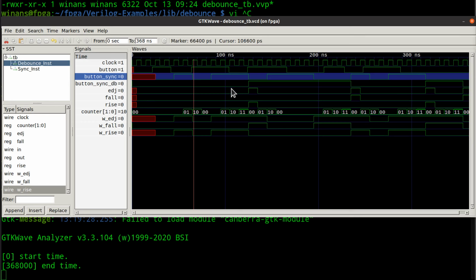Okay? This is a pipeline. All right? When I first started working these, even today, it can get very confusing. What the heck's going on? When did something happen, and at what point does it actually manifest itself in some recognizable way? So here's what's going on. The synchronizer went from 0 to 1 here, and that's our input to our debouncer, okay? So the debouncer doesn't see it. In fact, it doesn't see it here either. It doesn't see it until this rising edge.